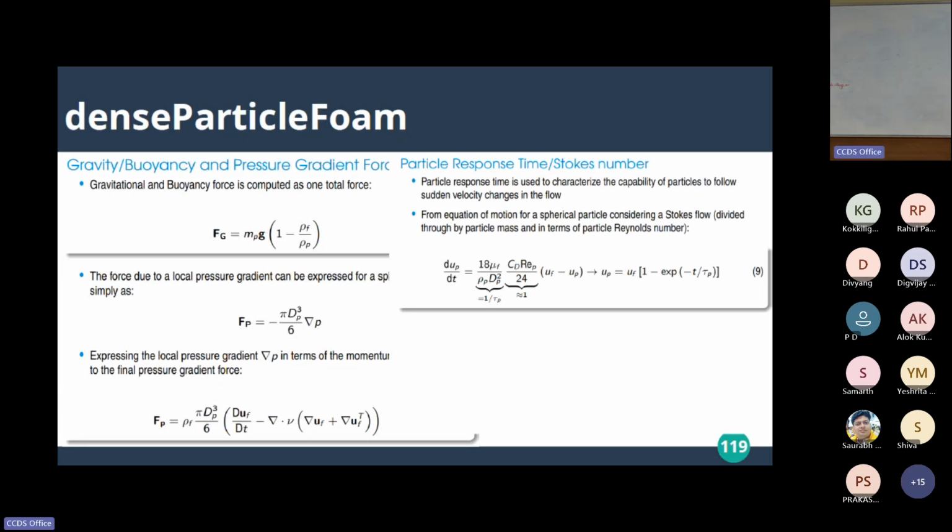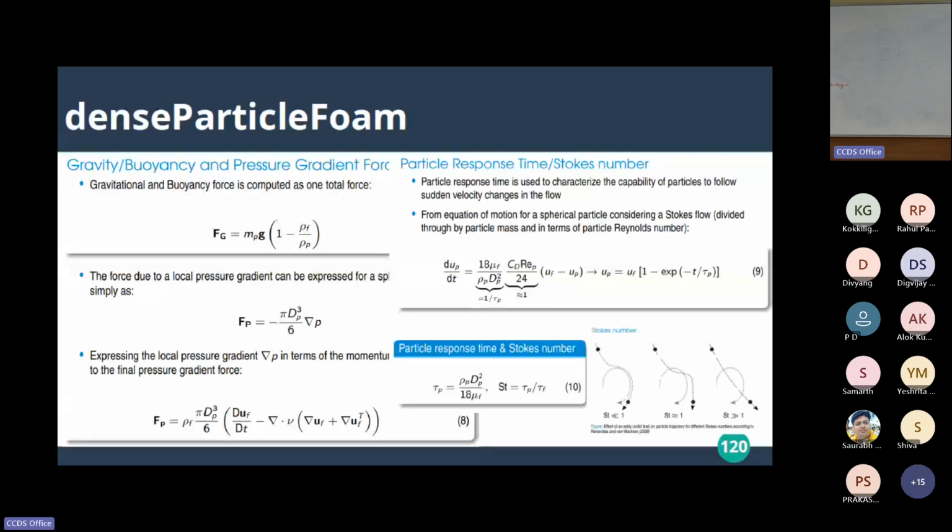And including all these things, people try to sense whether I really require all those contributions or some of the things I can really chuck out. People do that based on a number named the Stokes parameter or Stokes number. It tells how quickly an object becomes accustomed to the flow. If it very quickly becomes accustomed to the flow, it basically acts like a tracer. So your Stokes number will be very small. Skip some of the terms. Now if the particle has its inertia, it can't so easily take a turn even when the flow is trying to take one, so it influences the flow. Then Stokes numbers are large. You include certain terms. That is the way people tweak it.